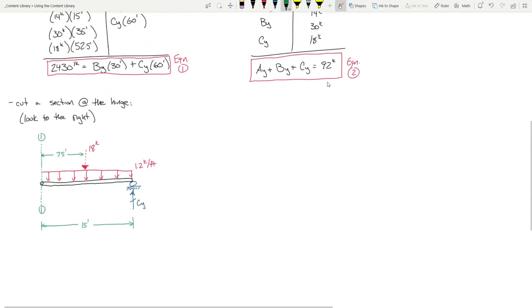The other thing is I need to indicate those unknown forces inside the structure at the hinge. And so what I'll do is I'll call those, I don't know, Fy, and we'll call that Fx. Now, I'll go ahead and tell you, I have drawn those in the direction of their positive sign convention. If I were to have drawn them in the opposite direction, it would not affect what I'm about to do. So right now, I don't want you to get too worried about that. But later on, that will become important. And when that becomes important, we'll definitely be pretty rigorous about that.